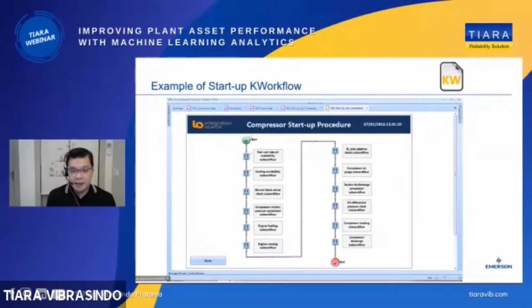But it can be a complex one, like what we did for Saudi Aramco. It can be a complex interaction between operator and DCS. Some steps of the workflow that get triggered when an abnormal condition happens can interact with the DCS, for example perform a startup or a shutdown, of course prompting the operator to check certain things before the system sets a particular value. It can write to the DCS, read from the DCS, prompt the operator with the required alerts, and show instructions on the DCS panel to do certain things. This enforces a standard operating procedure to be followed whenever an abnormal condition is detected.